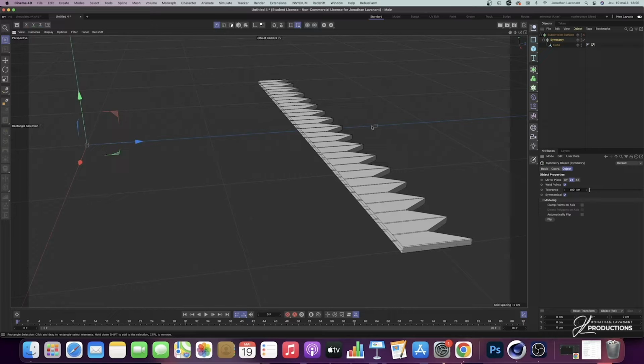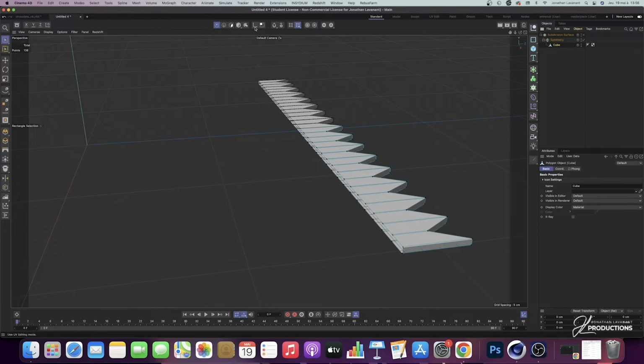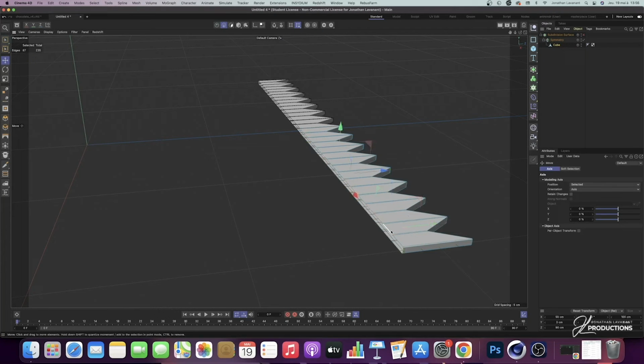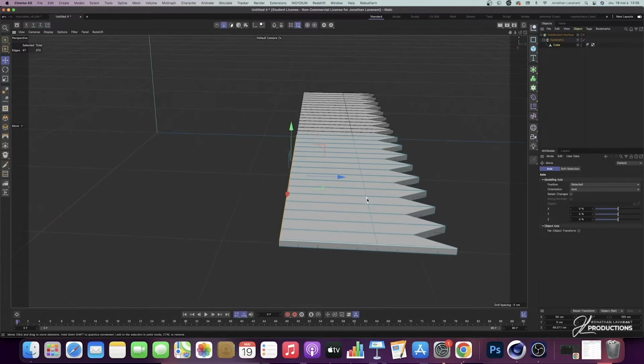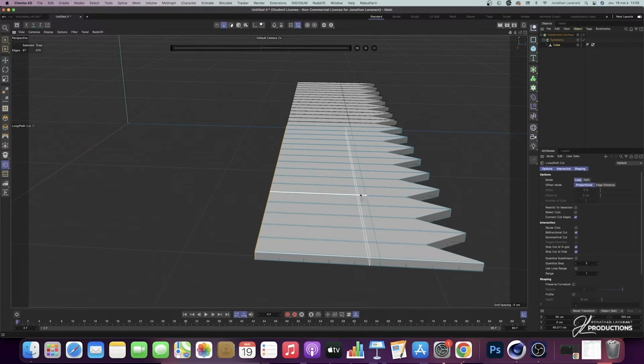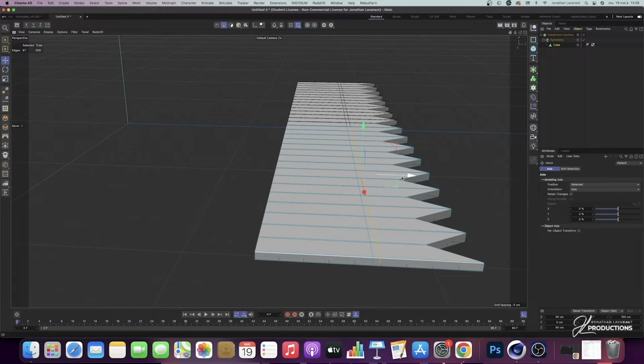So I'm going to select my cube here. I'm going to come in edges mode at this level and select the whole loop, which is right here, and I'm going to do a translation on the z-axis, the blue axis. Like this, I'm going to be able to add a loop cut directly, so I press ML. And I want to add a cut right here, and I'm going to be able to take that by double clicking and bring it closer to the edge like this.